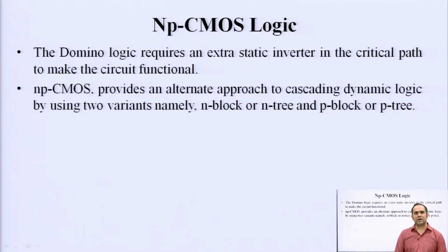But if you implement a logic only using N type devices, it will work in many conditions, but there may be certain conditions where there might be issues related to signal integrity, signal strength, and the effect of noise, because an N channel device is going to have a positive threshold voltage.